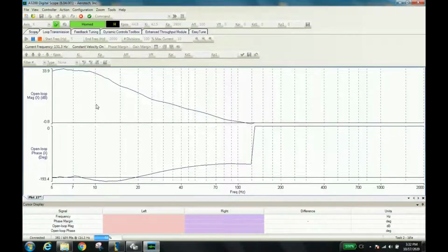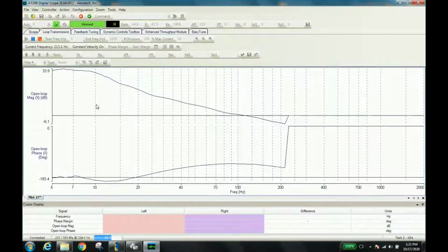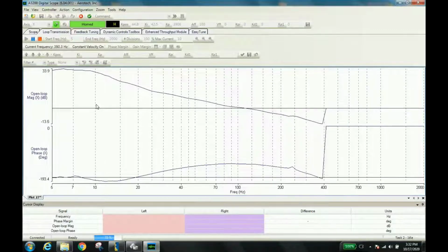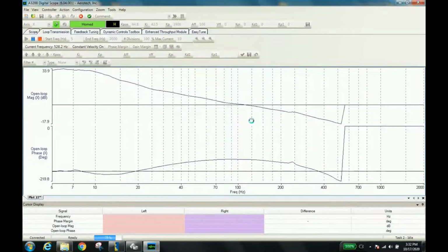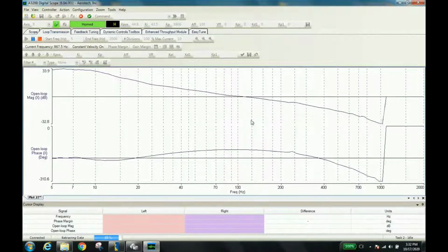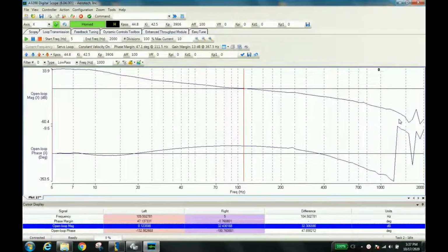As we did before, we would look at the gain and the phase margins, have the gain margin be more than 6 dB and the phase margin more than 30. What you'll see is this is a very robust system and it's stabilized with sufficient gain and phase margin. There's not a complicated load on the motor, so not a lot of dynamics out here at the high frequency, but we do notice a flattening of the curve here at the lower frequencies, which indicates some friction in the system.